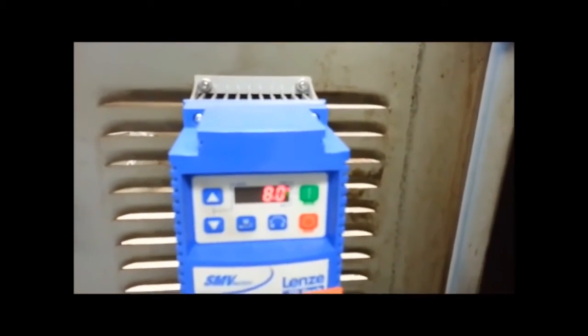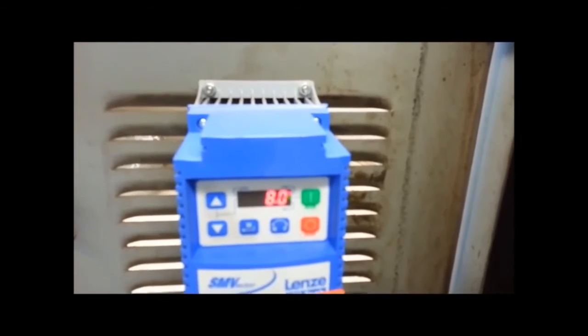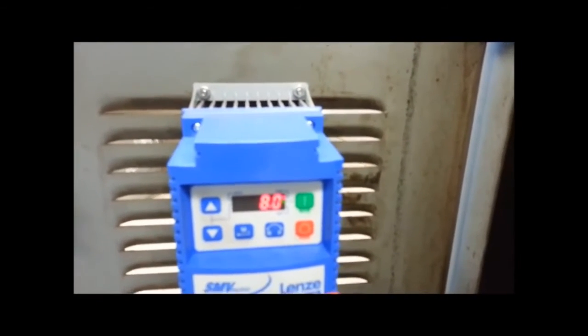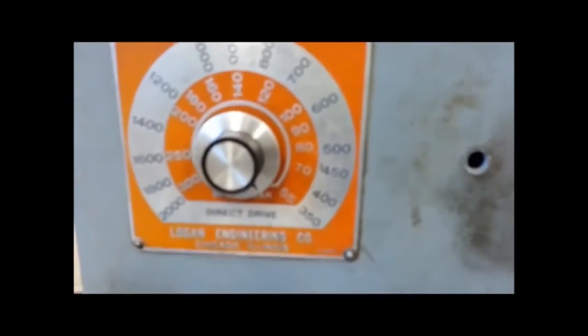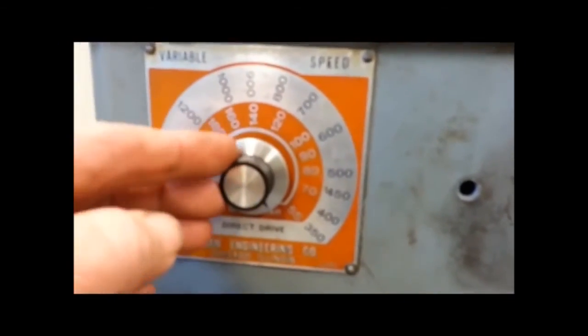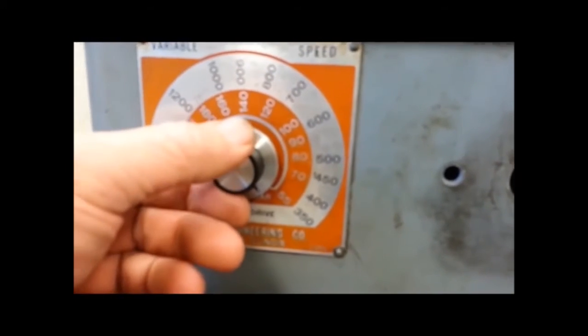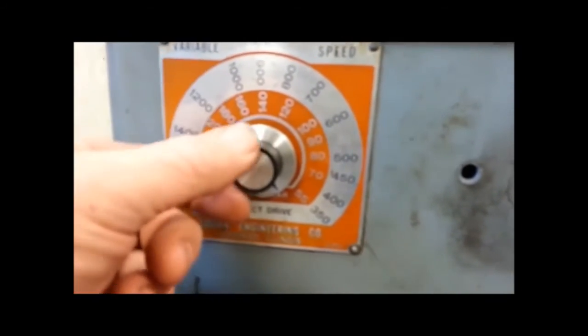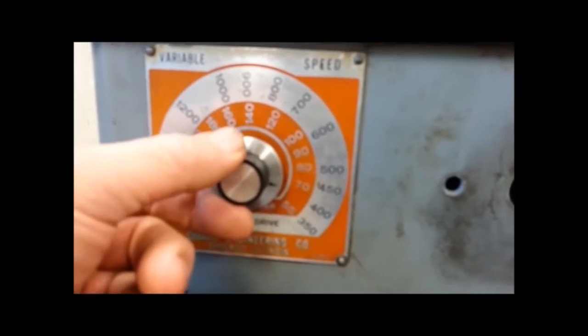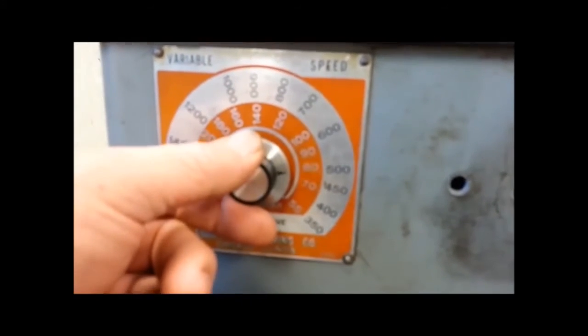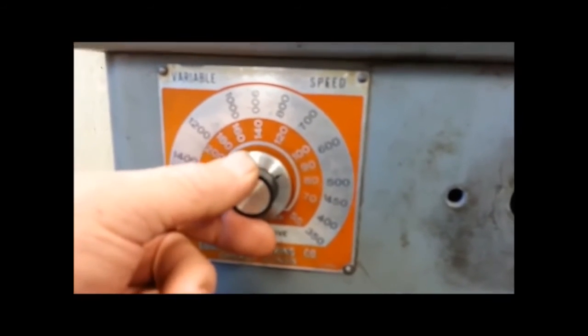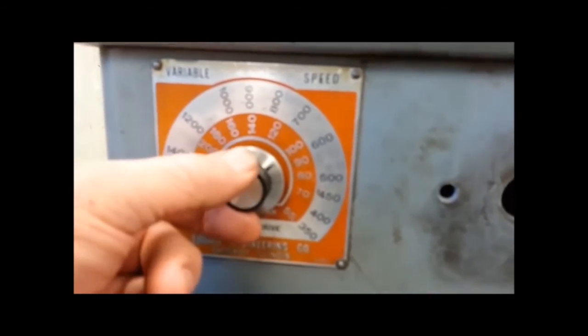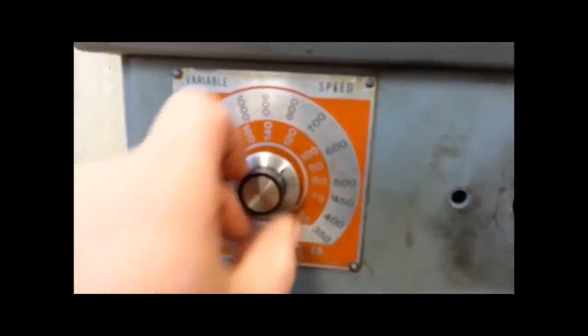And these units are nice. You can make the display whatever you want. Right there, that is referencing hertz. So that is running at 8 hertz at my minimum drive speed there. And here I just have, you can go to any electronics store and get a 10K pot, and they've got nice little knobs you can put on them. But you can hear I'm bringing up the speed of my lathe right there. And she'll go all the way to 2,000.